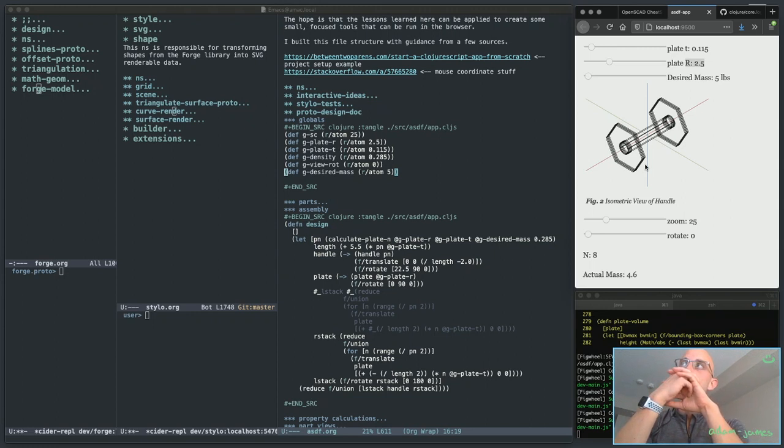Then you can weld those together like I said, and then you can take a grinder and grind everything smooth so there's no hard edges. Grind any flakes off the handle part, and then you can seal it somehow if you want, and just generally clean it up. But for prototypes, keeping it a little rough and tumble isn't such a big deal. Yeah, so that's pretty cool.